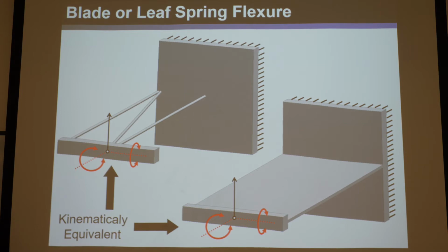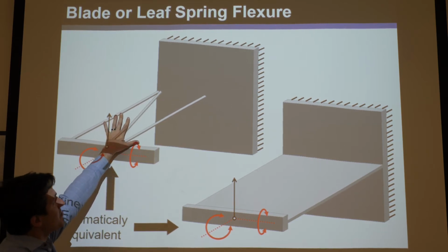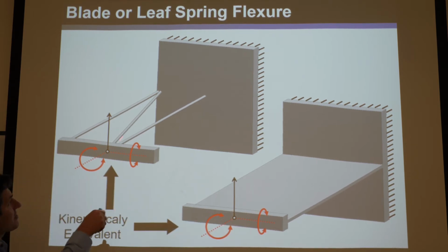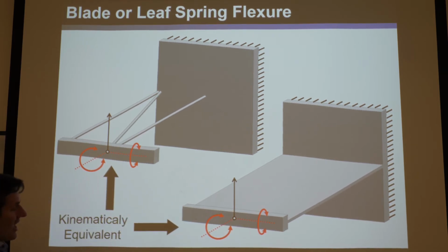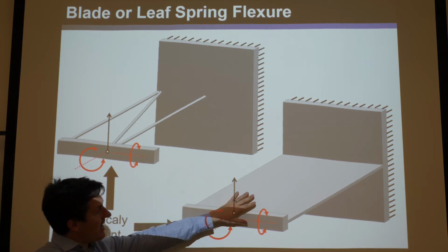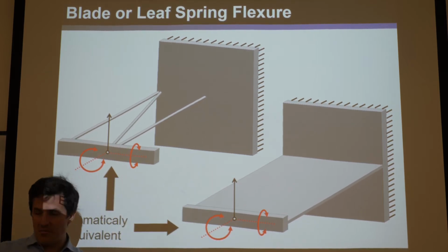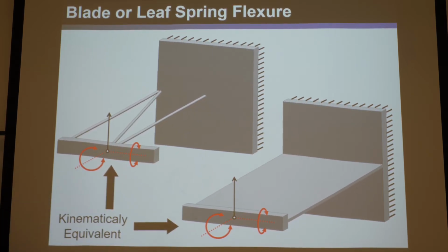They have the same kinematics, the same degrees of freedom. They both can twist, bend, and translate. Kinematically equivalent. Okay? But this one is more exactly constrained than that one. Right? Because this one actually had 3 wires, and they exactly constrained it. Whereas this guy was filled with, so far as we're concerned, infinite wires in its plane that made a nice thing. And so this one's over-constrained.